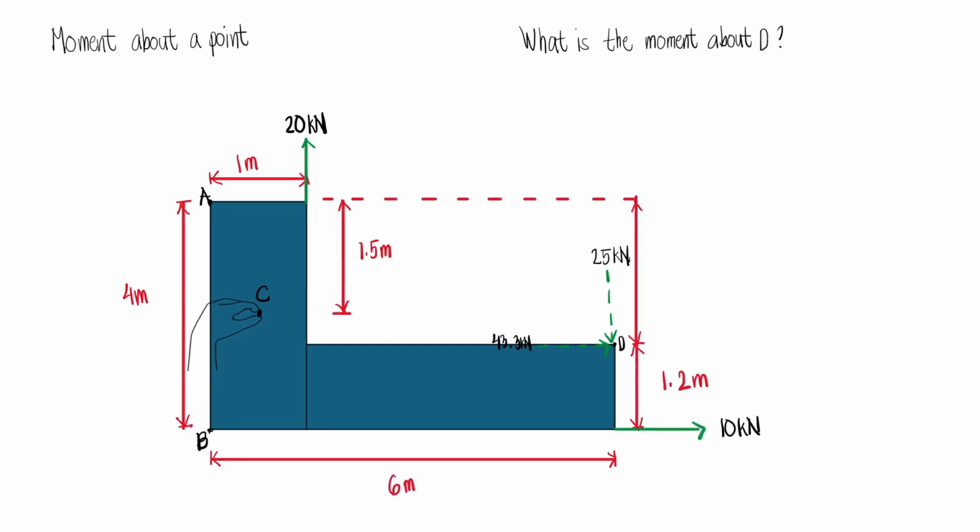And so we have this one. Now this is a bit challenging because our point is not right at the corners. However, the concept will still be the same. We will still multiply the forces by the moment arms. And so our MC will become, now let's just assume that this is at the center, so this is 0.5. And so we have minus 20 and then times 0.5.